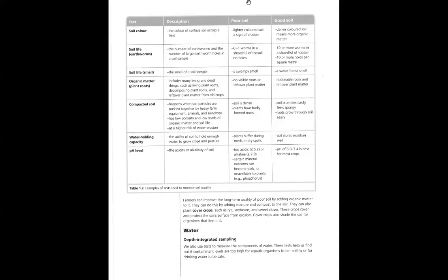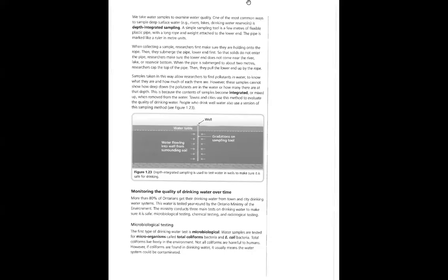The depth integrated sampling of water and how that works, where we lower a pipe into the water, careful not to touch the bottom, and then pull it out, and it gives us an idea of what's in that water, and that we continue to monitor it. Remember, we do samples and then we monitor. That's what we keep doing. Okay, and that's how we can find what's in the water.